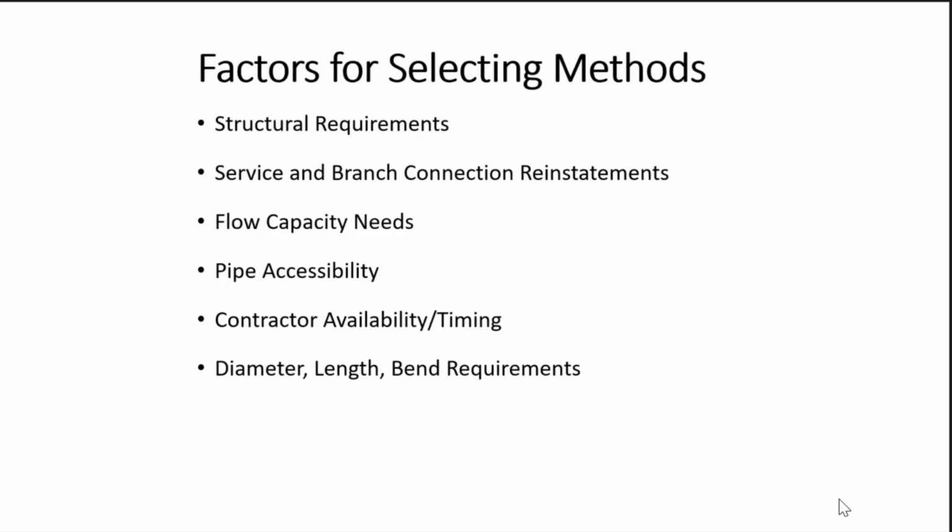And I know Ian threw up a quick slide there about the important things to understand if you're going to try to choose something. So I just wanted to throw this up so that you could kind of tie it back to the limitations and benefits that we talked about for each one. So if you have a pipe, does it still have structural carrying capacity? Meaning maybe it's just leaking, but in general it's withstanding all the loads. Or do you have a pipe that's on the verge of collapse? So that might lead you towards one technology versus another, right? If you just have a leak, you focus on that. If you have a pipe that's about to explode, you're going to need to apply some additional structural capacity.